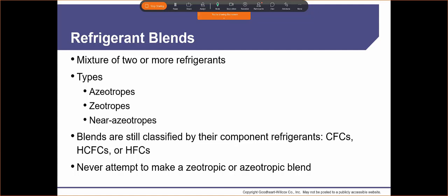If I were to do that with 410A, because I have 3 different types of refrigerants, what's going to end up happening is I'm going to have one refrigerant that boils off faster than another, and so I may end up getting a higher concentration of the first refrigerant, a little bit less of the second, and nothing of the third. Now all of a sudden my system isn't going to operate like it's supposed to because I have the incorrect mix of gases going into my system. So I may have basically created my own blend of refrigerant at this point.